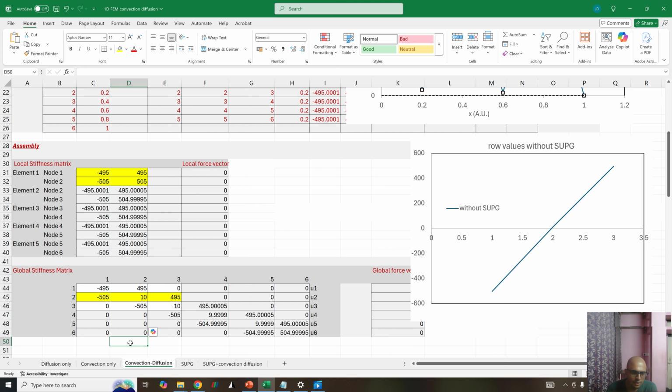That's the idea. In case of, for example, a lake which is still, if the pollution is occurring close to you, it will spread to you by diffusion. It doesn't matter in which direction it is occurring. But in case of convection, the direction matters. Here, if you look especially at these two terms, as we go from 1 to 6, you are going from upstream to downstream.